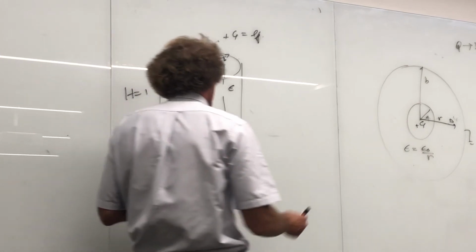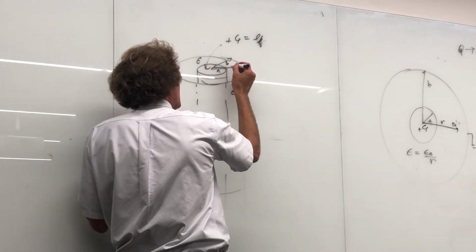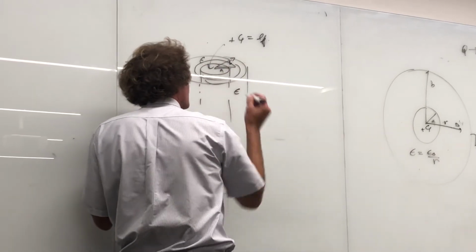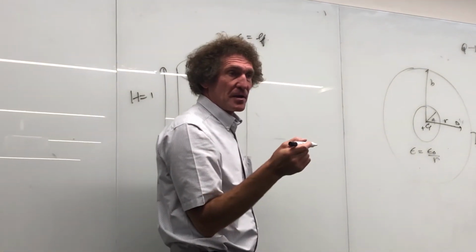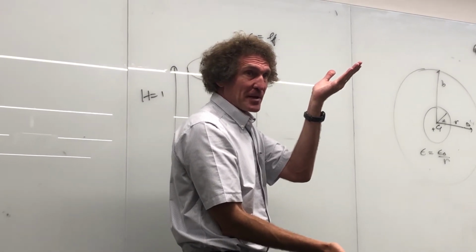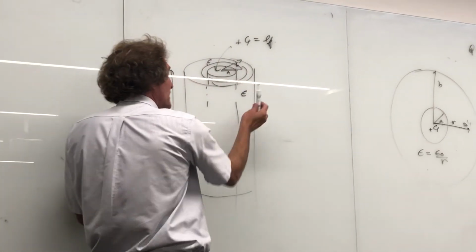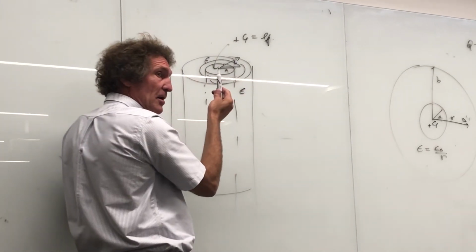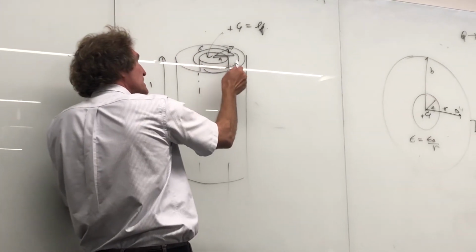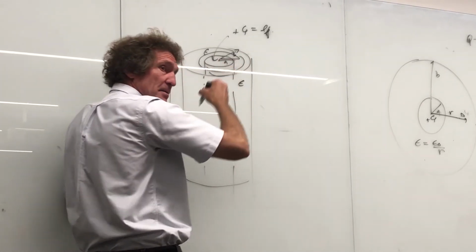So that's rho L. And that means, well, we could use Gauss's law, but how many remember what the D field is for a line charge? Isn't this like a line charge? It's charge per unit meter. Well, the D field is always what? It's the charge divided by the surface area for a constant D field. Isn't that surface area just 2 pi times the radial distance rho times the height?